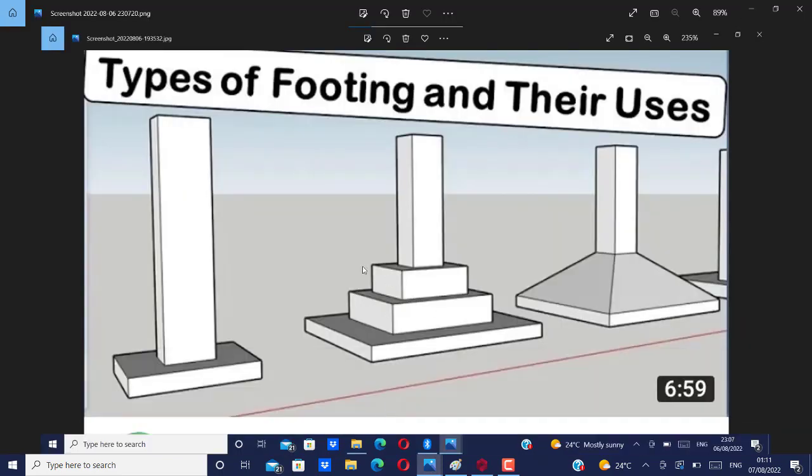What this image is trying to show you here is that because they have checked and seen that this particular thickness will fail under punching, instead of making this thickness, let's assume that this is a 450 all over. Under one-way shear, this one passed, this thickness was sufficient, but under punching shear check, maybe the thickness wasn't enough.